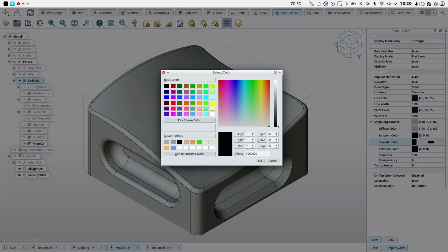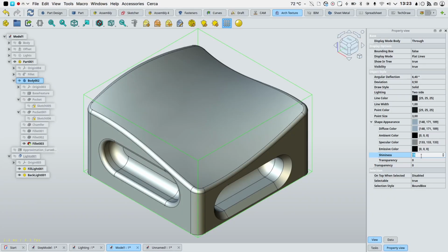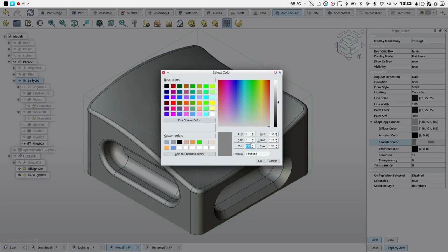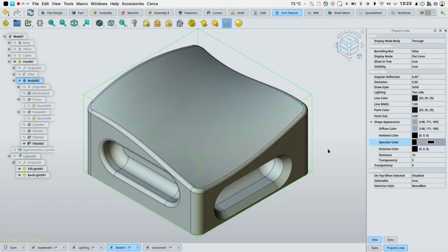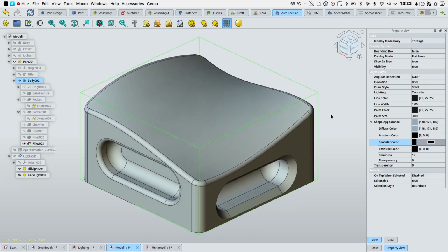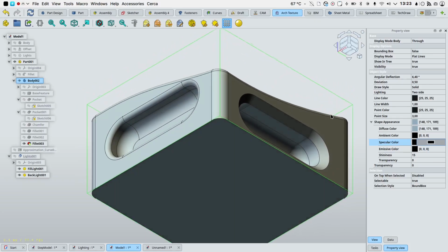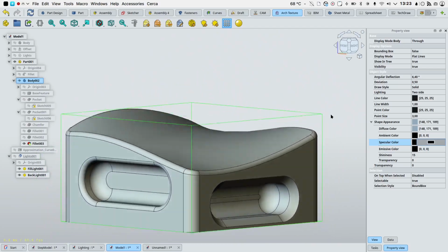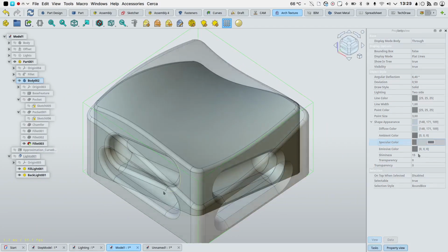If the value is set to a really low number, there will be almost no reflection on our geometry. If we want low reflectivity or even no reflectivity in our geometry, we need to select the specular color and give it a really low value. In this case, I will have it a complete black, and our surface will mimic a material like a really low reflectivity plastic.